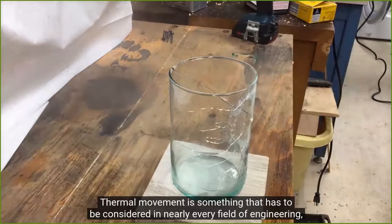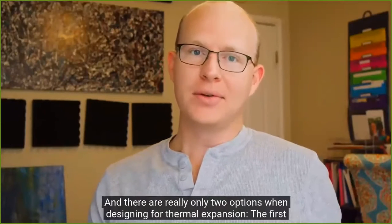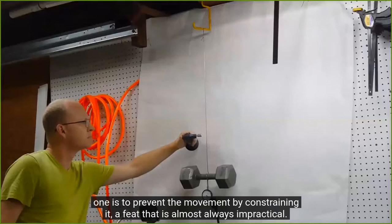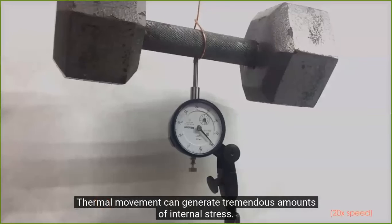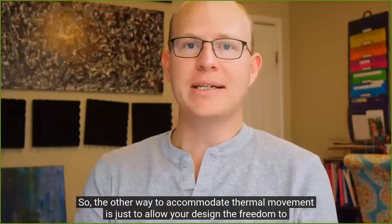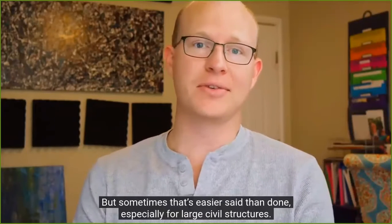Thermal movement is something that has to be considered in nearly every field of engineering, because there aren't many places that don't see fluctuations in temperature. And there are really only two options for designing to account for thermal movement. The first one is to prevent movement by constraining it, a feat that is almost always impractical. Thermal movement can generate tremendous amounts of internal stress. Watch how this wire can lift up a weight just by heating it up and cooling it down. So the other way to accommodate thermal movement is just to allow your design the freedom to move as it so desires. But sometimes it's easier said than done, especially for large civil structures.